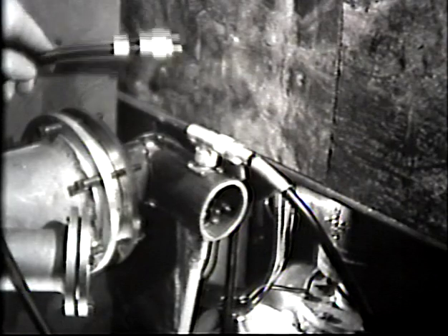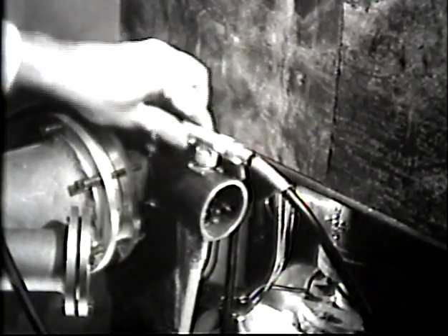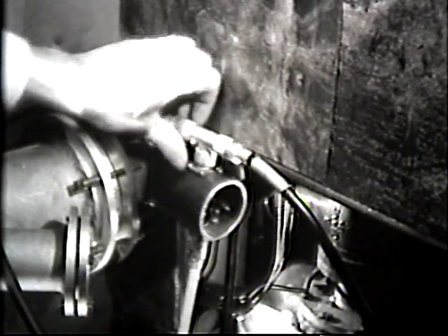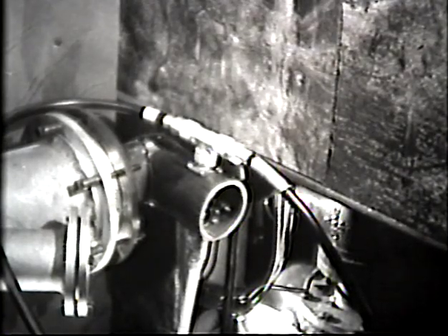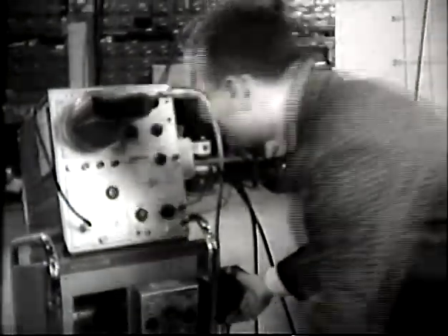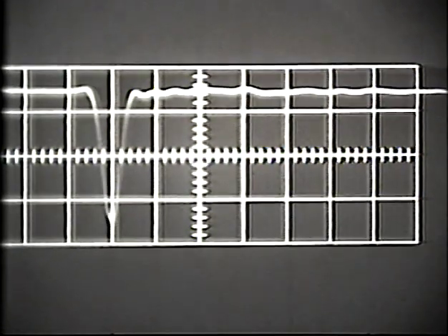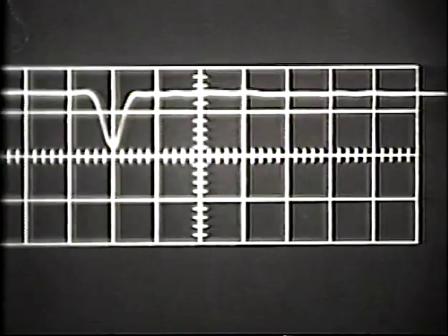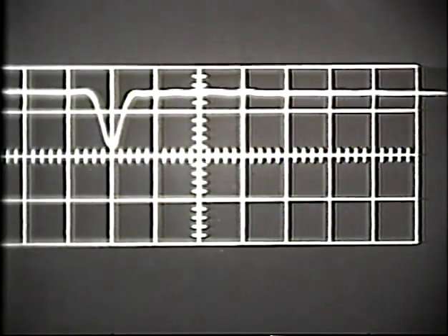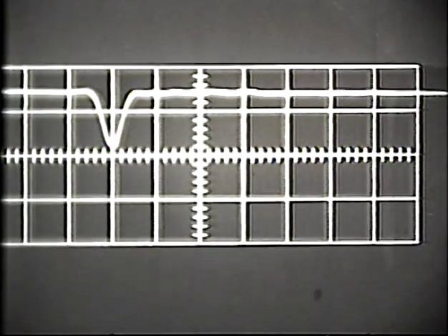I'll connect this second cable here with the first cable at the start position. You remember, the short white cable below carries the signal to trigger the sweep, while these longer matched cables will carry our timing signals. Now I'll turn the beam on again. You see one signal on the scope face. I'll disconnect this first cable. You see that the signal coming in through the second cable alone is in the same place as that from the first cable. I'll connect them both again.